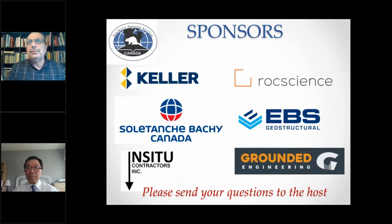But if you don't have enough slump, if you have a slump less than 150, for example, 150 millimeters, you may have this problem. So increase your slump and you will be okay. If you have water, or a slurry, or a polymer within the hole as a drilling fluid, you need to use a tremie. You can't have a free fall. So segregation using the tremie